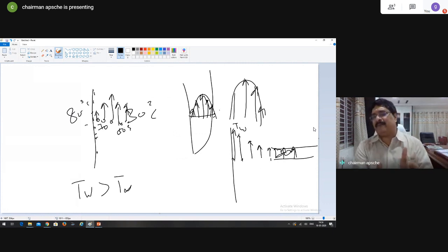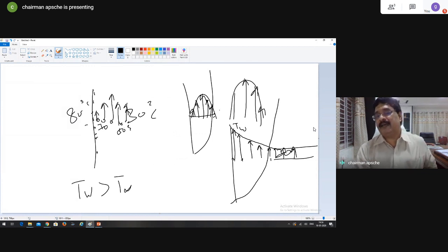The temperature effects, or thermal diffusivity or heat interactions, are not felt beyond this distance. So the temperature profile is this, and when you join all such points where for the first time the temperature becomes 30 degrees centigrade, this is the thermal boundary layer. This is the hydrodynamic boundary. Even though in natural convection the fluid is not literally moving, right in the vicinity of the plate, because of the temperature variations and buoyancy forces, the fluid still moves in an organized way in a particular direction.